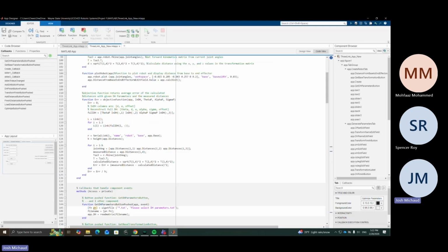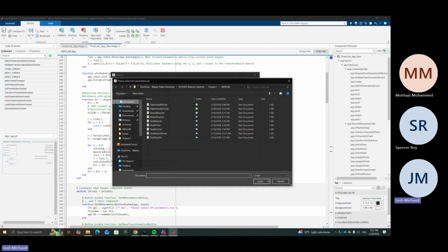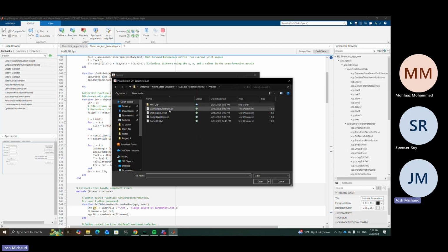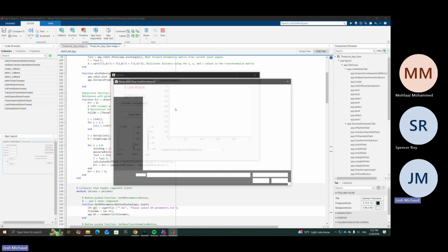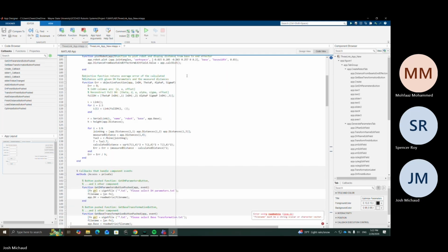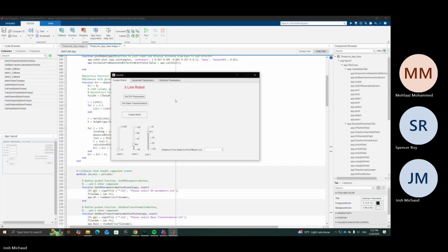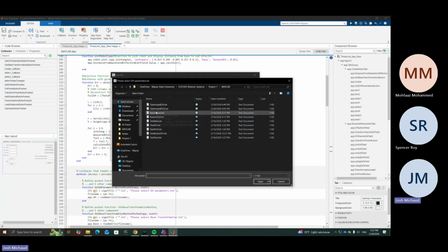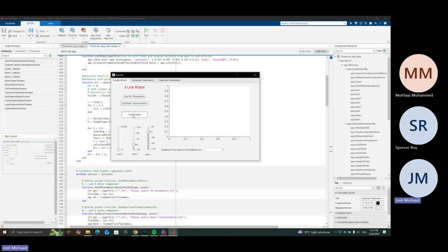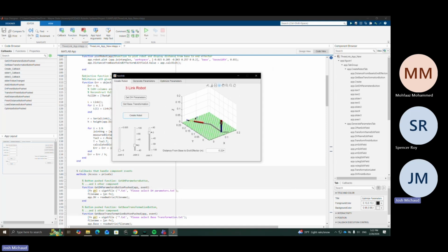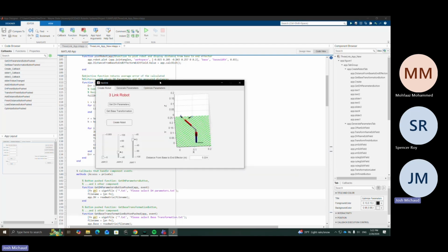What it output was a bit strange, so here, let me see, DH, oops. Okay, so you have our optimized DH parameters and the base, and it optimized it in a weird way, so it must have found some strange solution, but it is more accurate than before. But this did run into some issues using the fminsearch method. But other than that, everything works correctly.